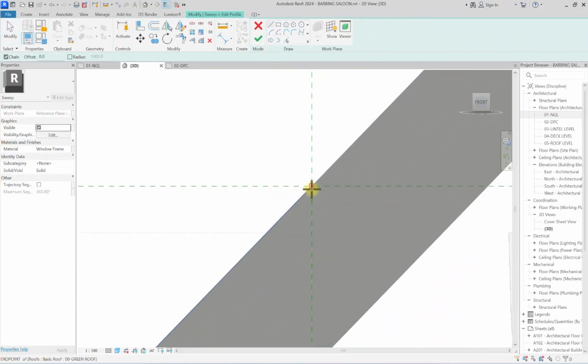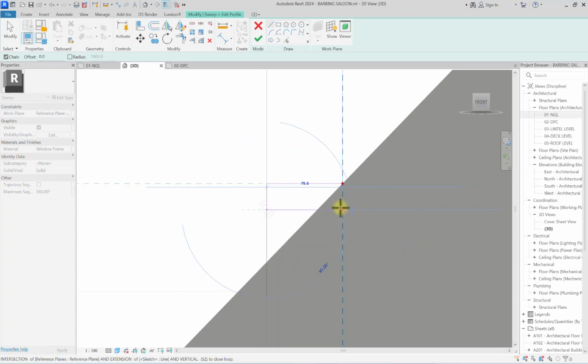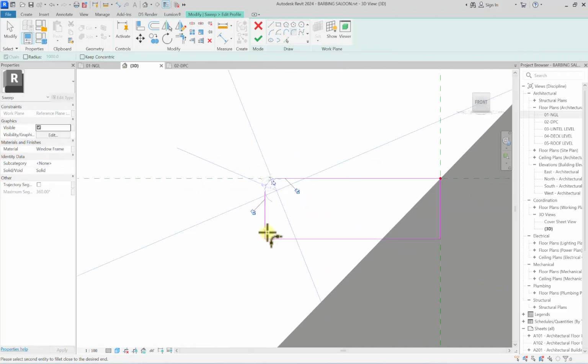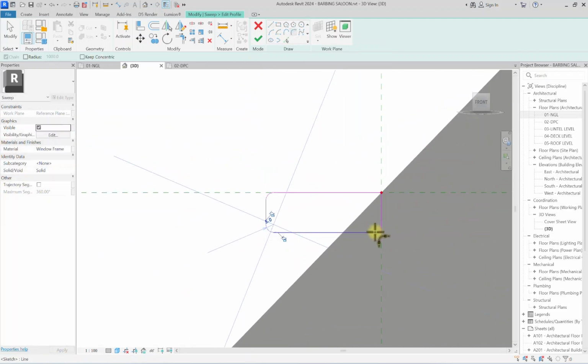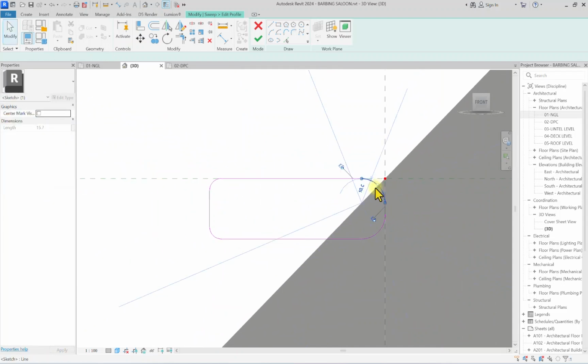Then I'm now going to start drawing our panels. So I'm going to draw one here first. This one will be up to 75 millimeter, down to 25 millimeter, back to 75 and join this. So I'm going to click on this fillet arc tool. I'm going to fillet here as well, fillet here too, fillet here too. Then I'm going to click on all these arcs and change it to 5 millimeters. Click on this 5 millimeters, here too 5, click on this 5.